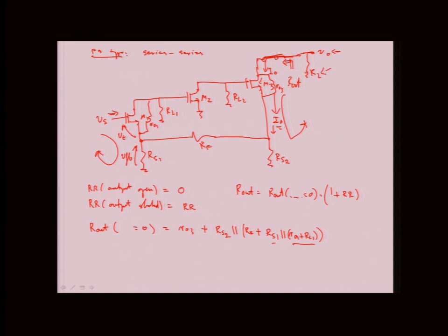So in the remaining few minutes, let's go back to the same circuit and do the A equivalent because we haven't really done it for this type of feedback. So for the return ratio, we're going to null the input, and we have the V test that we apply here.